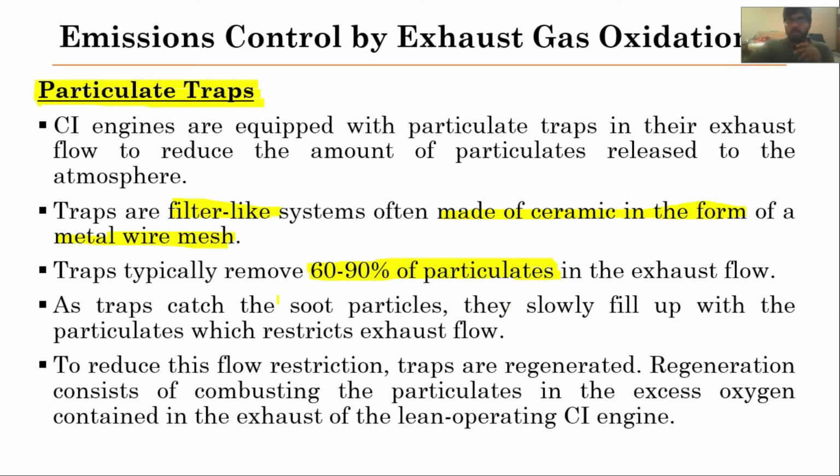And so with the passage of time, they will slowly fill up, and then it will restrict the exhaust gas flow. So for that purpose, the traps are being regenerated, and regeneration consists of combusting these particulates in the excess of oxygen. So this is what will happen for the regeneration purpose.